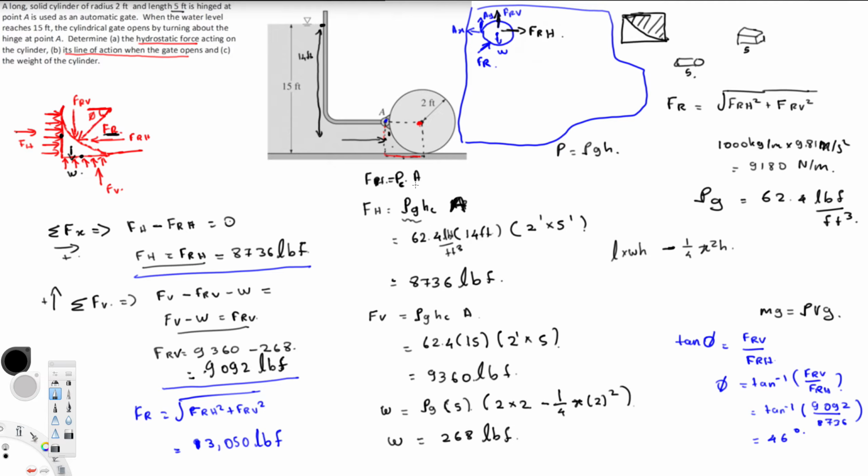So we have two components right here, and that's all we have. Now we have to find the weight. Because we have AX and AY, two unknowns, we don't even want to find this unnecessary thing, so we can simply eliminate it by taking the moment around it.